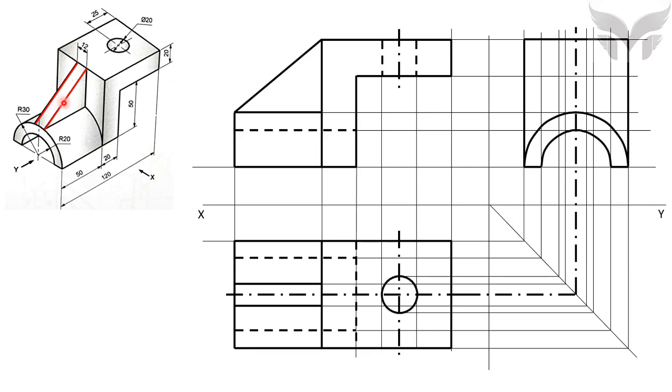So to show rib in side view, we need to draw two vertical lines which are 12 mm apart. Here you need to look out for the projectors of rib from top view and show rib on the same projectors like this. Done. Till now we have shown everything what we see.